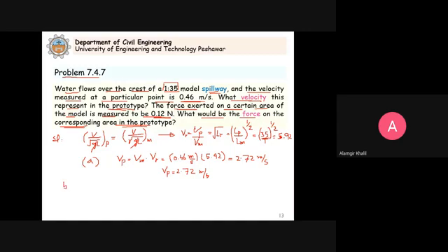So you need to develop the force scale ratio. So how can we develop this force scale ratio Fr? This can be considered as the ratio of inertia forces, because inertia forces will be present in both model and prototype. So from there we can develop this. This will be for the prototype and this will be for the model.